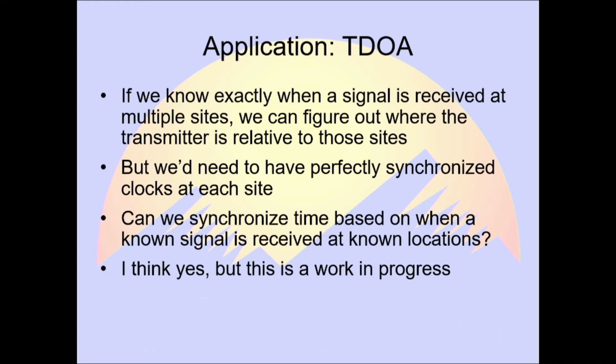So I think the trick is going to be we need another reference transmitter at another known site. Since we know the distance between our known transmitter and our receivers, we should be able to figure out the time delays between the different receivers and calculate exactly relative what time it is, and then based on our signal of interest, figure out where the signal comes from.